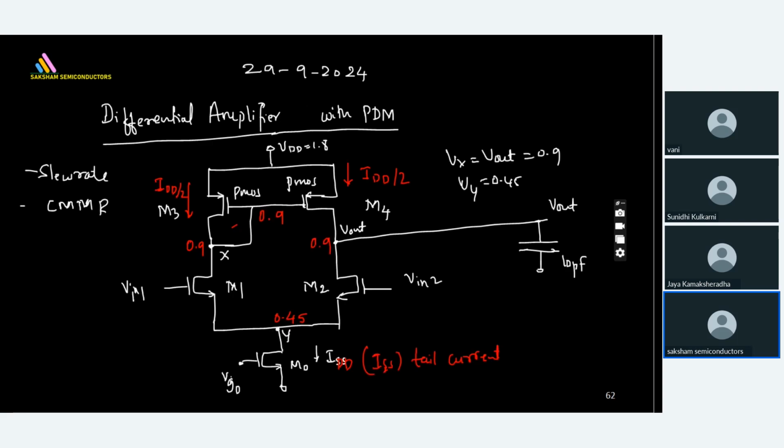So now let's go into the other step. First consider M naught. How does M naught look? Let's see here. This is the scenario where your source is grounded, drain is at 0.5 volt, and I need to find VG naught. So let's mark it. This is M naught. So here it is 0.45. This is ground, and I'm going to apply the same formula.